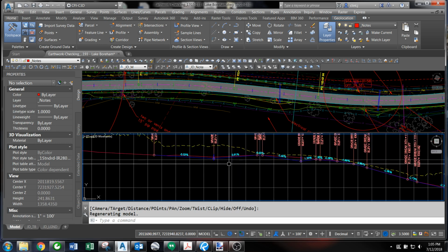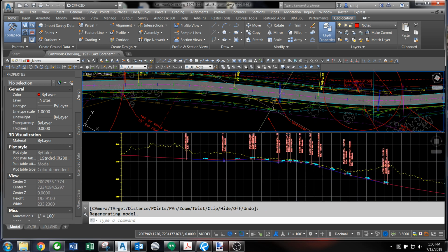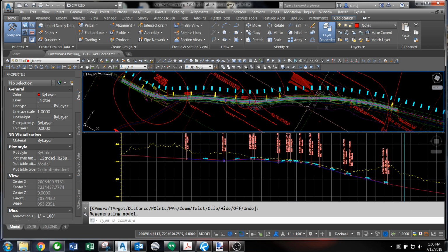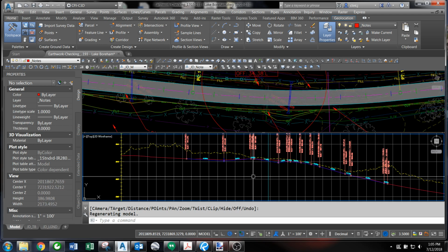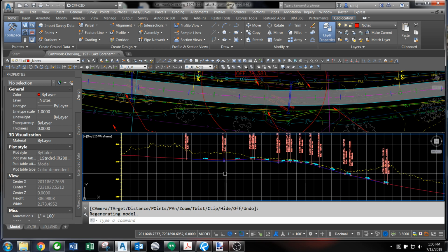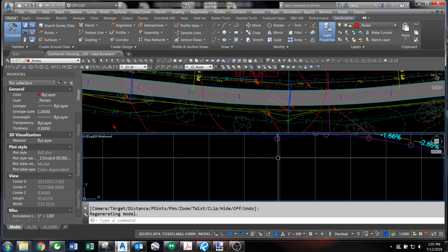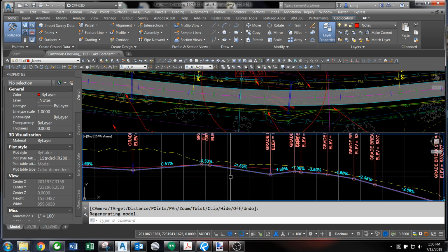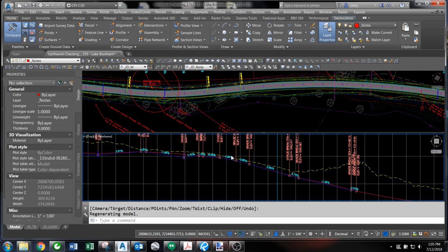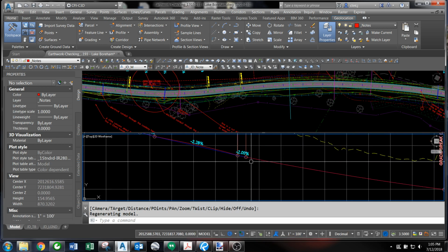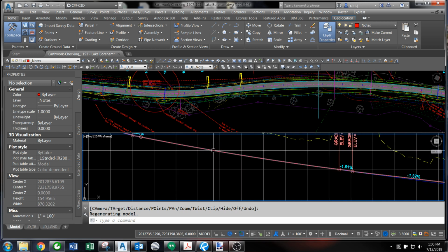Anyway, this whole ditch along this, basically most of line A, was actually designed rather than just letting the typical section and center line dictate what's going on. So you can see it. Here's a low spot in the culvert, here's a low spot in the culvert, and we're putting these low spots in the ditch. We're actually controlling the ditch. Once we get around here, we're happy with what the ditch is doing on its own.